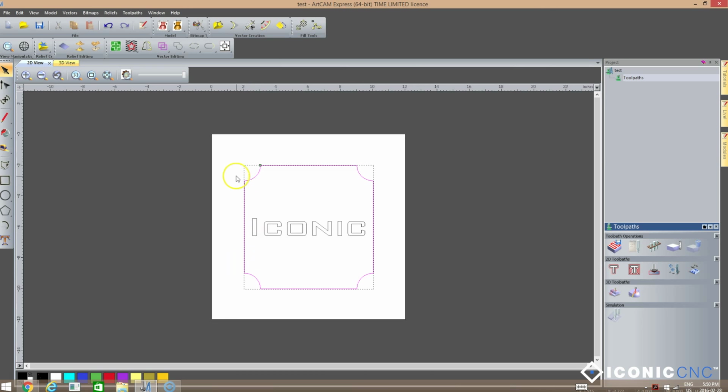So let's say that I wanted to create a picture frame where I'm going to take the center portion of this out and the outer portion is going to be my finished product. Then one of the options in Profile Toolpath is to select inside the line, and that's exactly what I would do. So in other words, my tool would rest on the inside of this line and it would machine all around here so that I would have exactly an 8-inch opening on my picture frame.